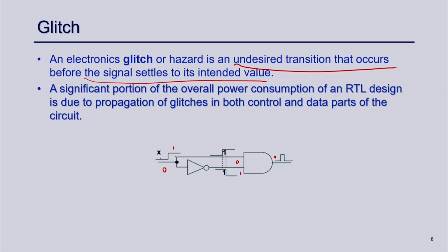So, I have now 1. Similarly, immediately this 1 is available here, but since there is some combinational circuit here, it may not come at exactly the same moment here, right. That means earlier it was 1, because x was 0, it is 1 here. So, for a moment, this is also 1 and this is 1, and the output of this AND gate will be 1, right. This is what is called a glitch, but this may last for a picosecond or something. But just after that moment this will become 0, and as this becomes 0, the output will become 0 again, right. So, this is what is called a glitch.